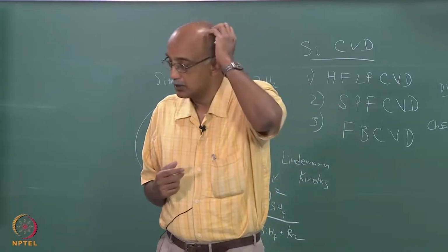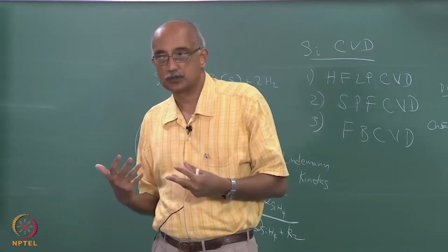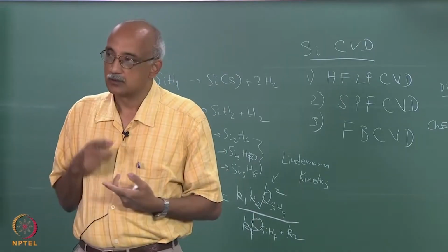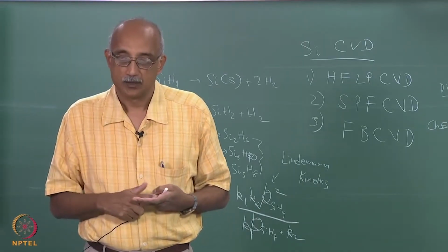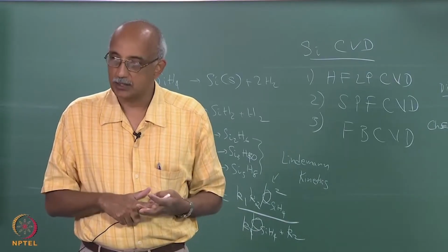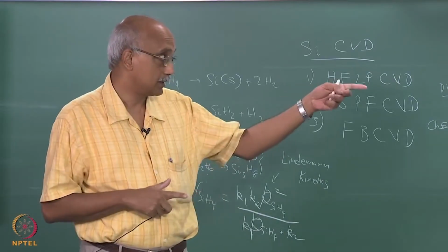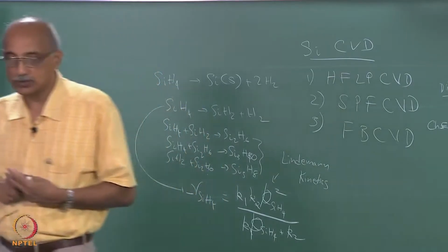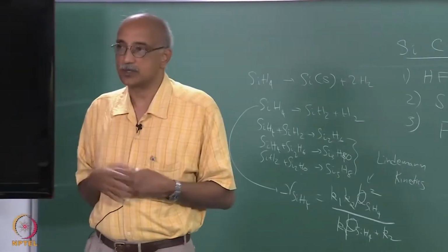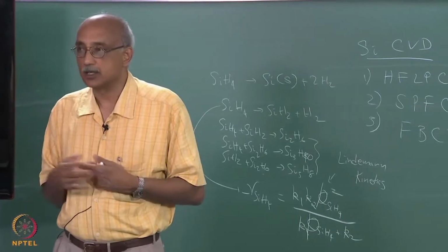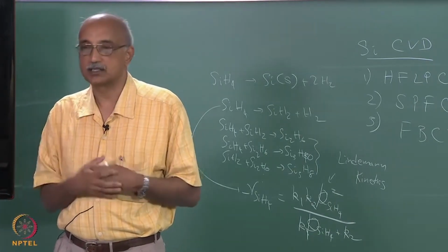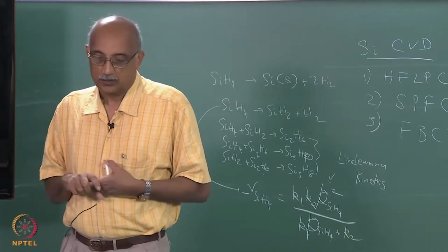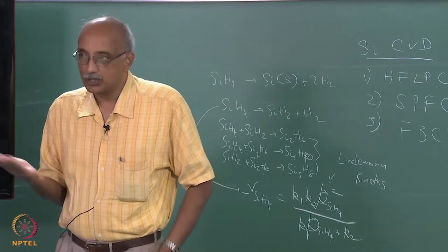So, if you are trying to model the CVD process as a whole for a fluidized bed CVD reactor, you would develop a first principles model for the flow dynamics and for the diffusion process, but then for the homogeneous kinetics as well as the heterogeneous kinetics that is presented here, you would tend to use these kinetic rate expressions that are experimentally derived. So, they have to be essentially fed in as a subroutine to the CFD model, which is okay, it basically becomes a UDF.